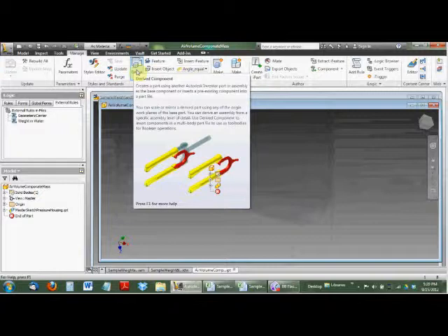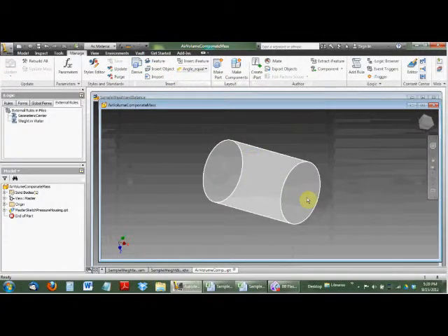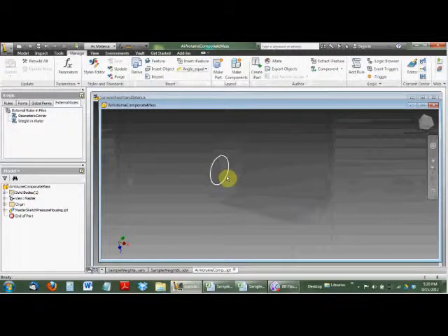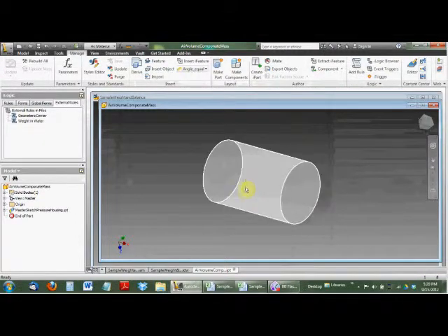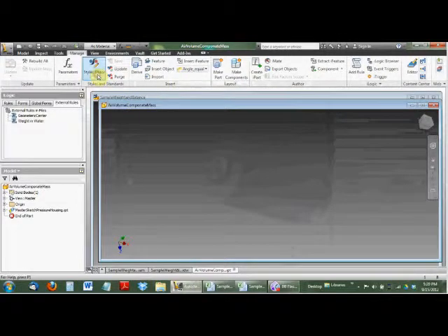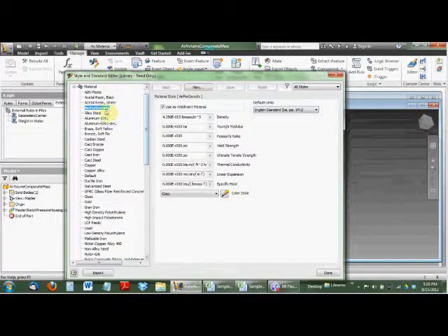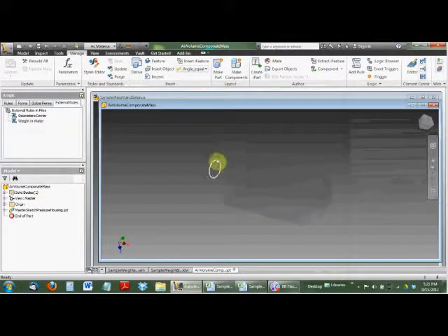It'll be the spaces in between the other parts in your assembly, basically, and that works well. In my case, I didn't do that. Everything was simple here. I just pulled this out of a master sketch, and I got this volume, and then I went to the styles editor and I created this density for air as a material. So basically this is the density of air. I've applied that and I've made it glass because air is clear or whatever. So basically that makes a nice pure air volume.